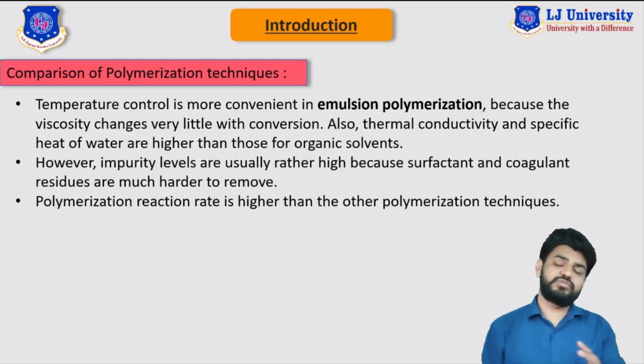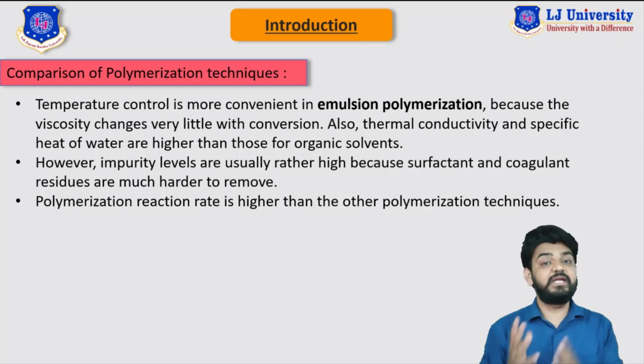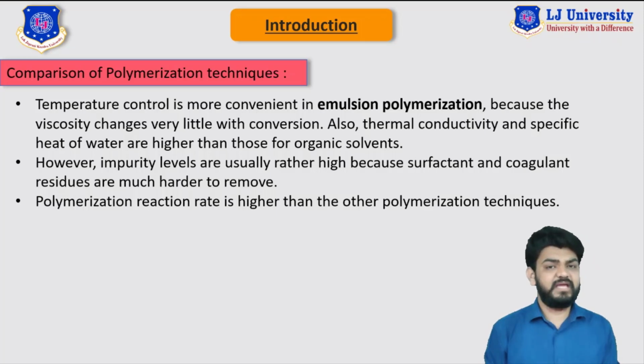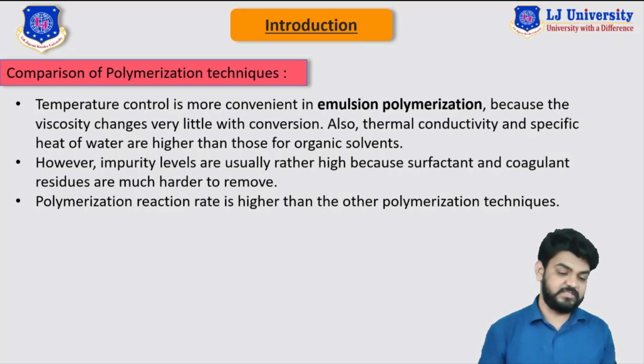So, we can use this water as the heat transfer medium, so that we can easily remove all the heat associated with the chemical reaction, right? So we can easily control the exothermicity of the reaction with the emulsion polymerization technique, and that is the major advantage of this emulsion polymerization technique compared to the other techniques.